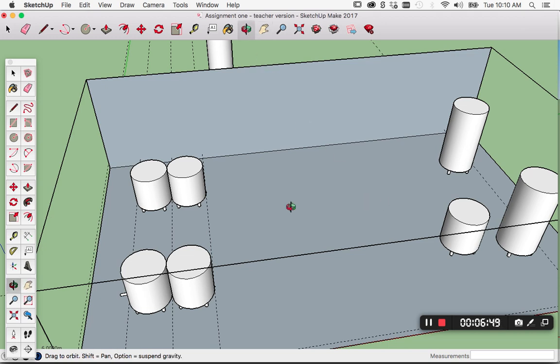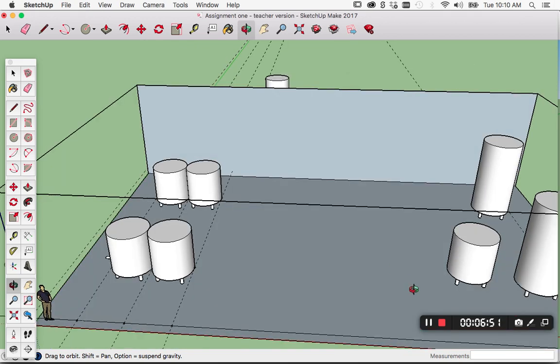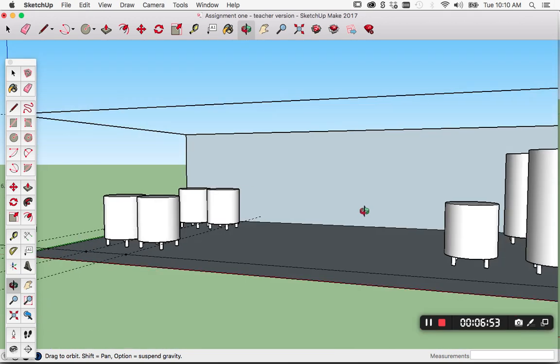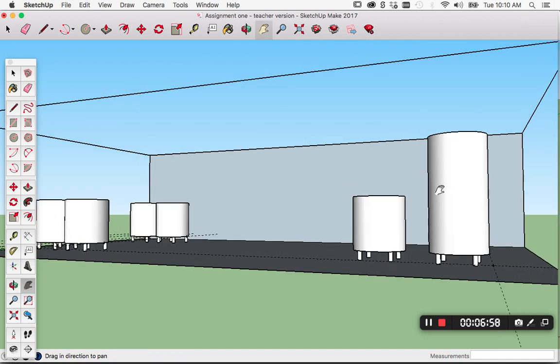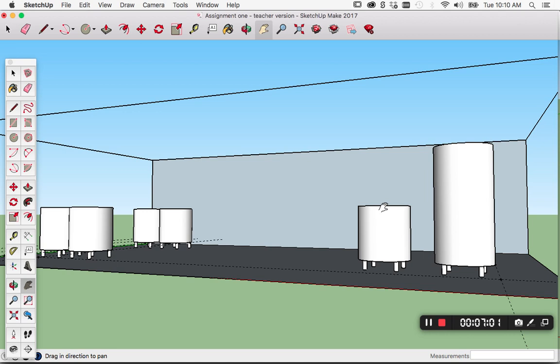What's the minimum static head for this transfer? Well, it'll be when the liquid is at its highest in the supply tanks. And that's because if we're moving the liquid from the base of these tanks over to the side wall, if the liquid in that tank is right at the top, then we actually get 2 meters of head for free, because that liquid will move via gravity along this pipe and then up to the liquid level in the original tank.